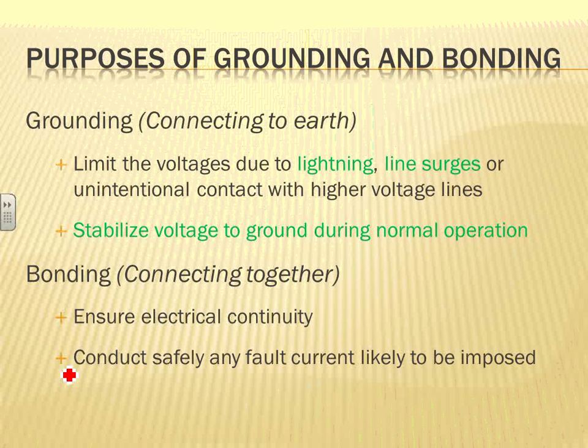Now I have a stable 277 because I'm bonding it to the ground. It doesn't depend on what happened on the conductor that's coming from the utility because it's already bonded to the ground. And also, if you have any surges in the system, if your system is grounded, it can handle these surges much higher than if your system is ungrounded. What's the problem with the grounded system?